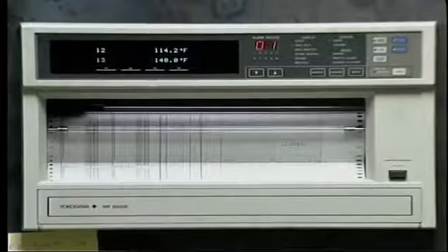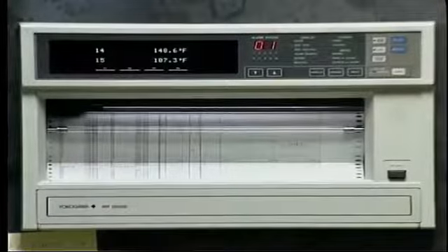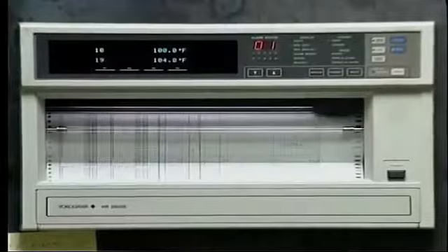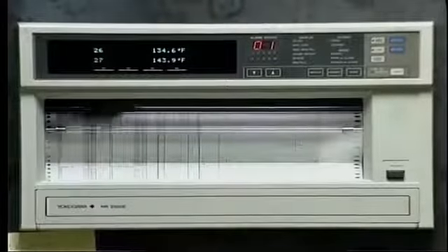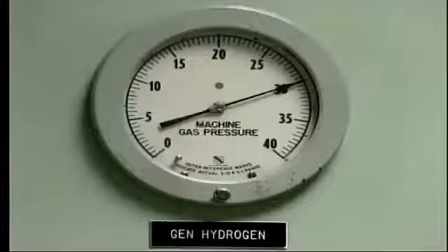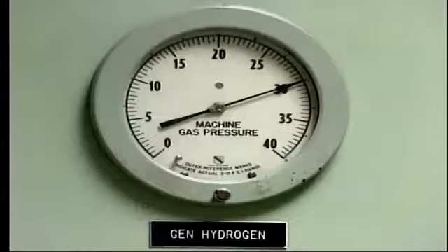If the internal temperature rises too high, it will damage the insulation and put the generator out of service. For this reason, distinct limits are placed on permissible temperature rise. In order to monitor this, temperature detectors are embedded in the stator windings at the anticipated hotspots. These readings are continuously recorded and alarmed when necessary. Forced cooling is employed to keep the temperature rise as low as possible, either by hydrogen cooling or air cooling. We'll be talking more about this in the next segment.